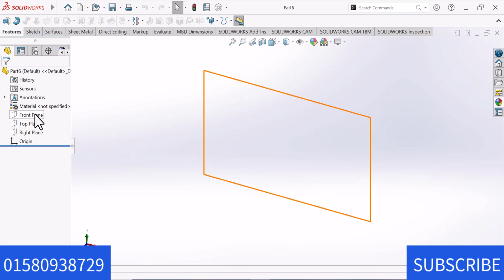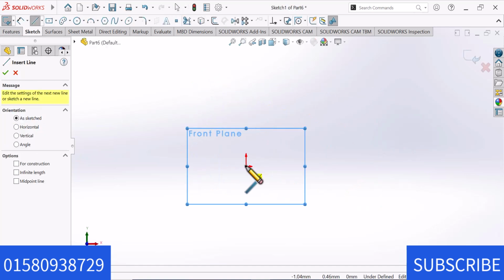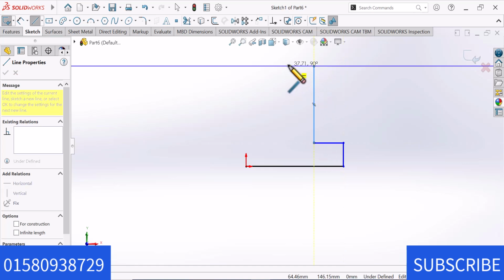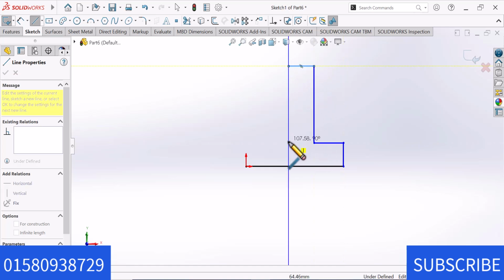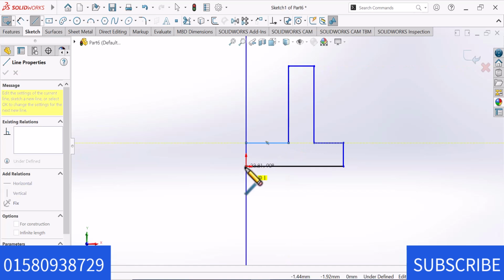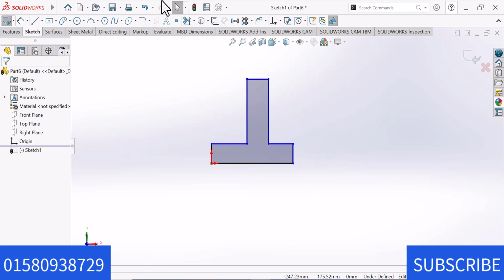Now select the front plane and sketch. Now draw the lines, horizontally and vertically, horizontally and vertically, and again horizontally and vertically. Okay. Now go to Smart Dimension.